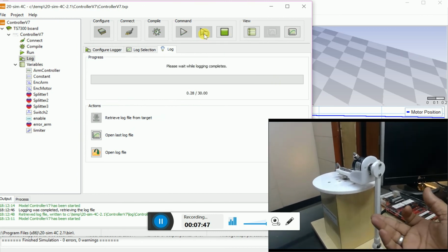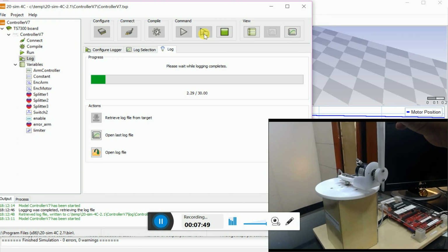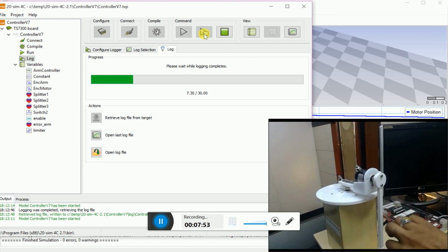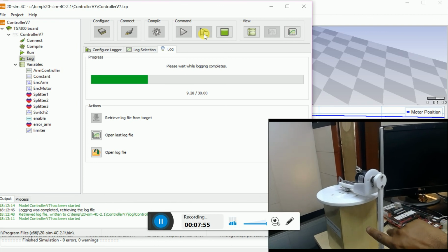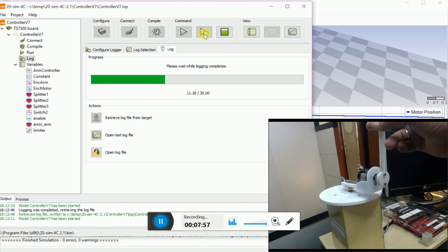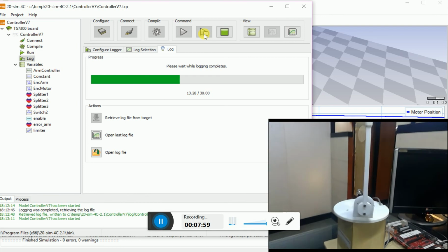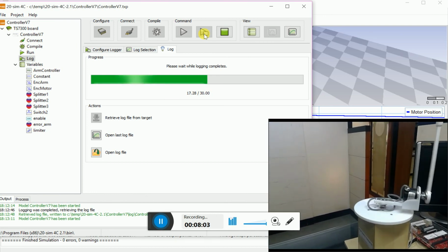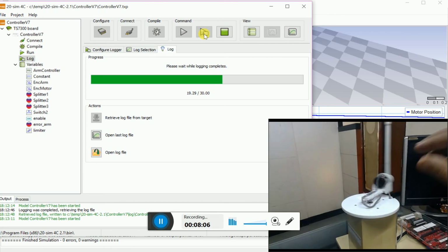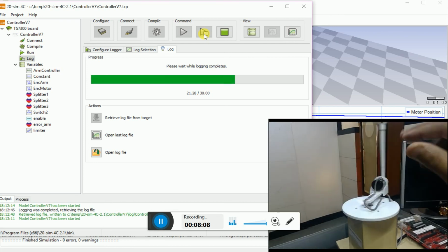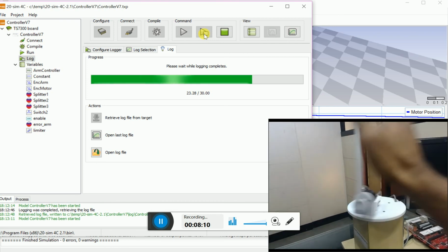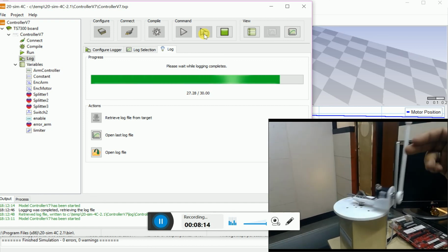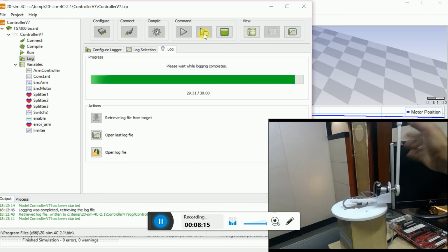If you move it anti-clockwise, you can see that the controller is not coming into action, because the angle is in the negative direction. So you have to put it clockwise and you see the controller comes into action. If you add too much disturbance, the motor will disable itself. For example, I added disturbance, so you see, if the angle falls too much, it will stop. But as of now, you can see that it is able to take a good amount of disturbance.